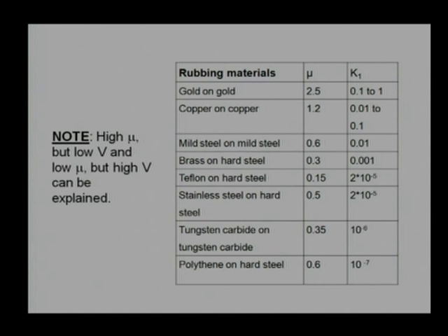Talk about 99.9% pure copper, no void, no inclusion. High coefficient of friction, maybe 0.6 plus, but wear rate will be low, because fatigue will not be there, there is no crack generation or void.